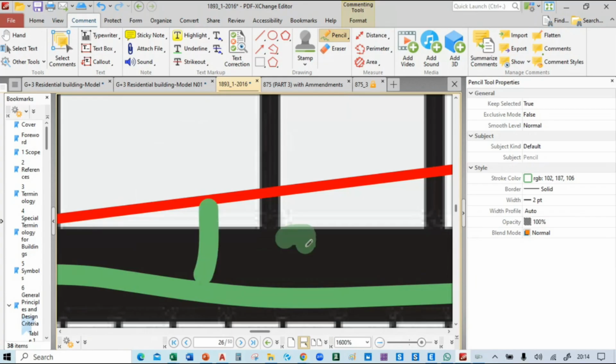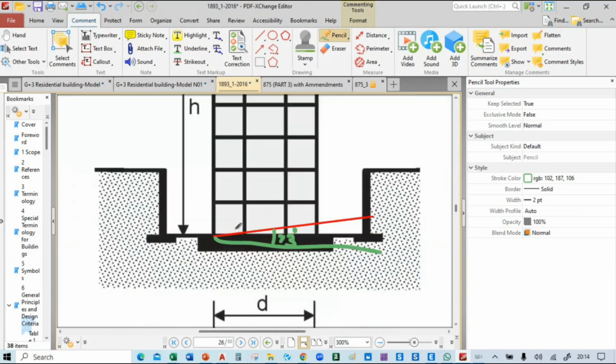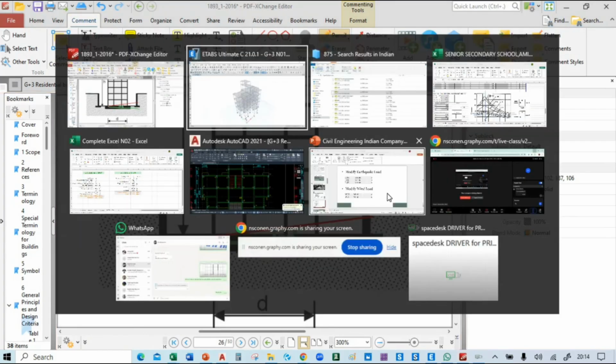If this slope is greater than 3, then we have to take the topography factor into account. But in our building, this degree is 0. There is no slope in the ground.